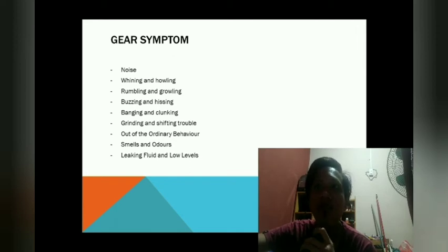Your transmission fluid level should stay constant, so any sign of this fluid under the car is an indication of a leak. To perform the fluid check, rest your machine for a short time in neutral before pulling out the dipstick without turning your machine off.